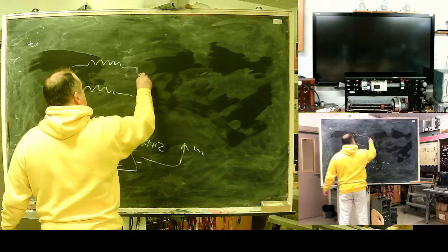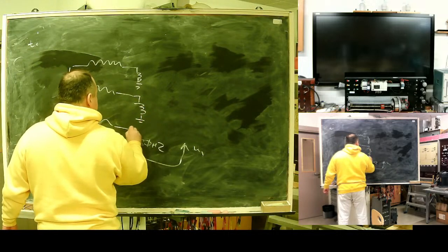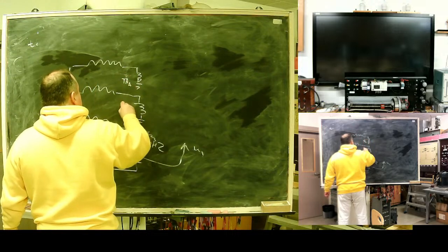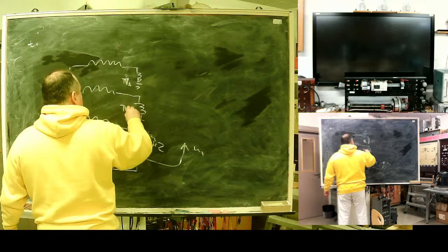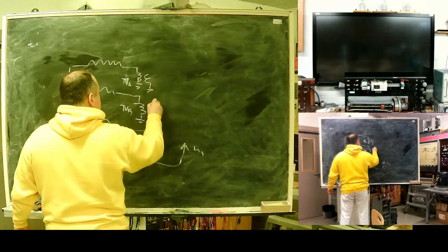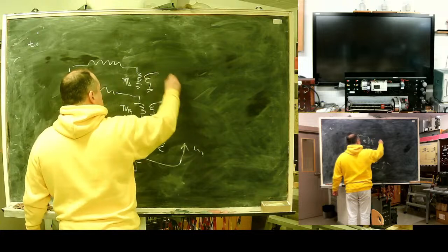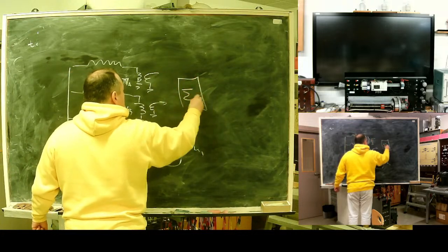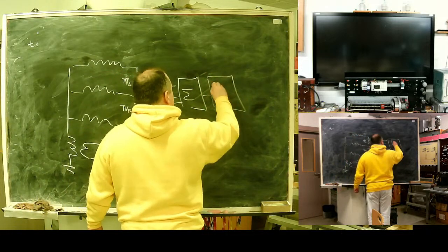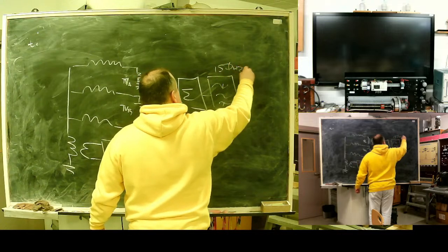From here, voltage transformer A, voltage transformer B, voltage transformer C. Phase voltages are taken to some function, and from that function again to a band pass for 150 Hertz.